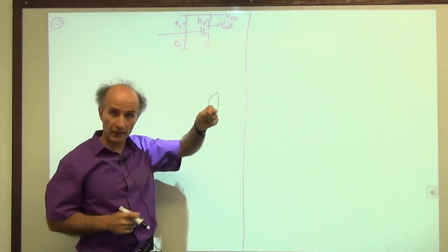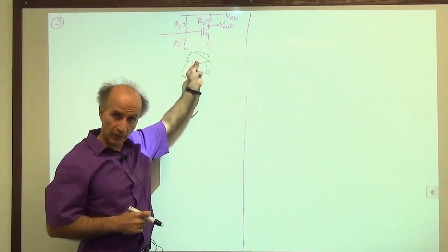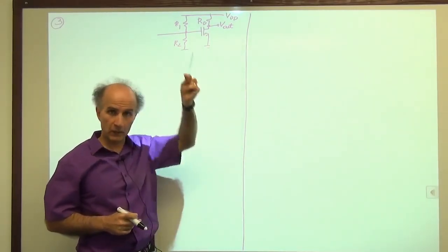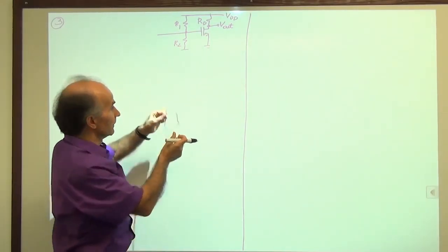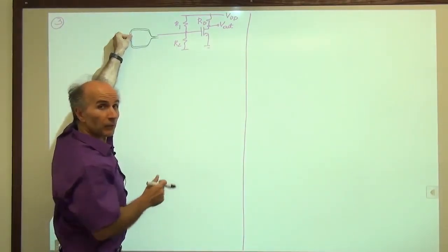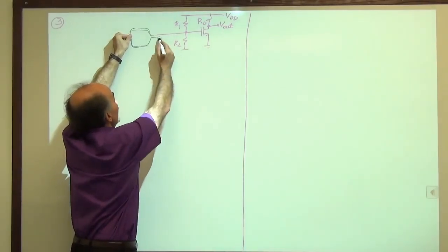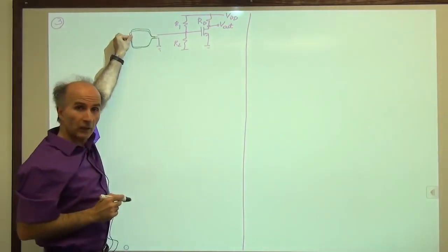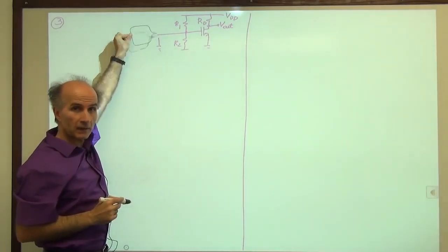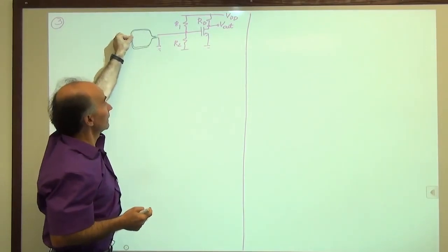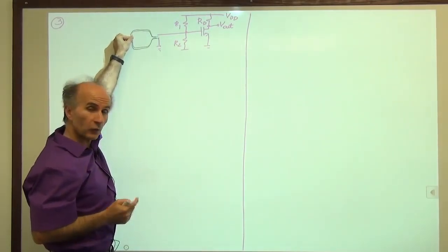And I would like to connect this to my LNA, to my amplifier, to amplify the signal that I receive from elsewhere. All right, so here's what we're going to do. I'm going to take this and connect it from here to ground, right? So one terminal connects to the input, one terminal connects to ground. Okay, I hope you can see the details, the antenna has 2 pins, and the 2 pins are connected like this. Now, do we have a problem?